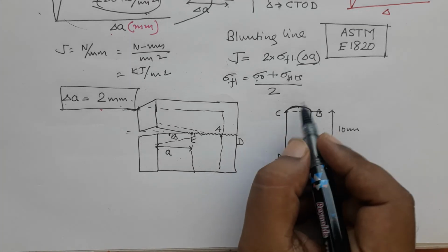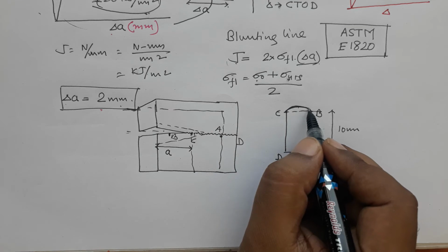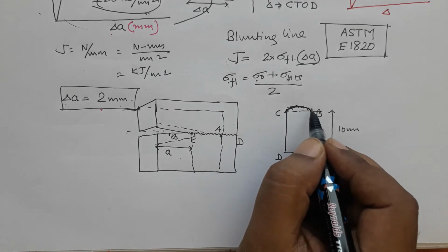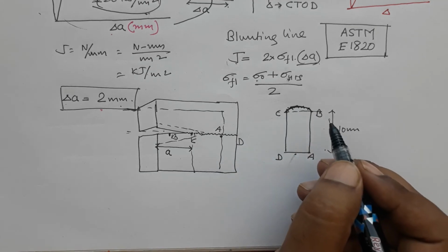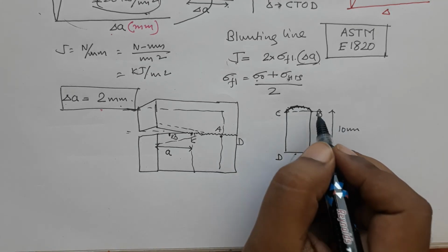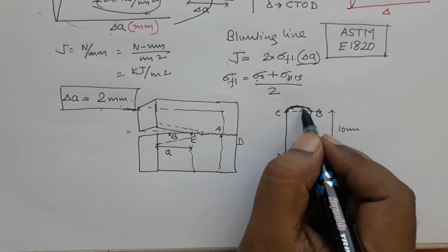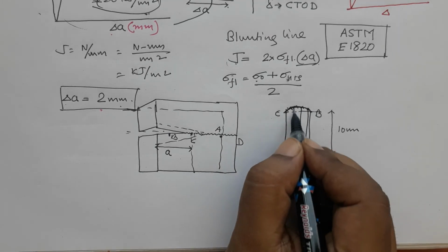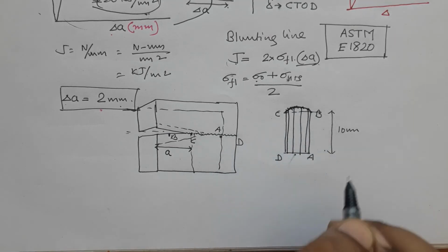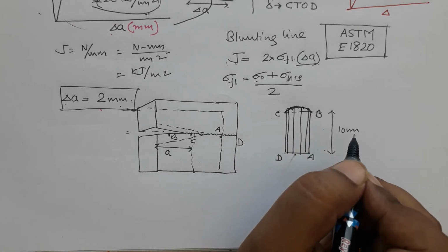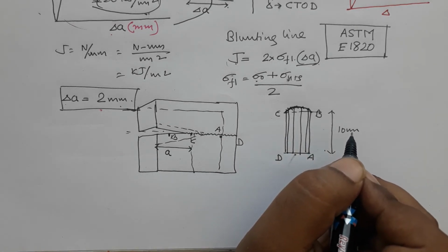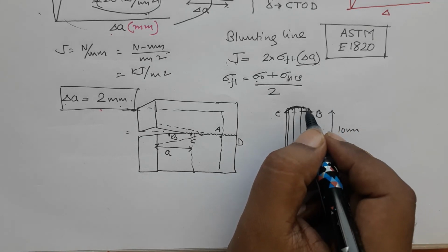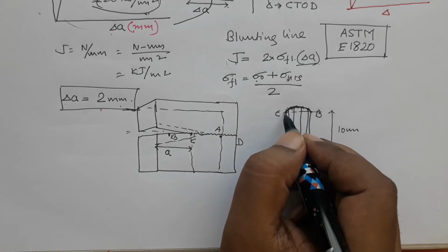values. So, you obviously will be measuring at certain points, right, and each one of us may take 100 points. Somebody wants to be very, very accurate, and so he will take 200 points and he will say so what is the length here and what is the length here, and then he will take an average of all those 200 values and he will be getting a different value in 4th decimal place, right. So, in order to standardize that process, ASTM says that you have to take 9 values